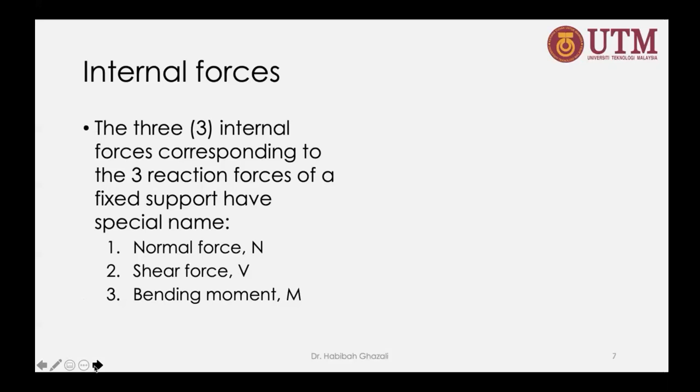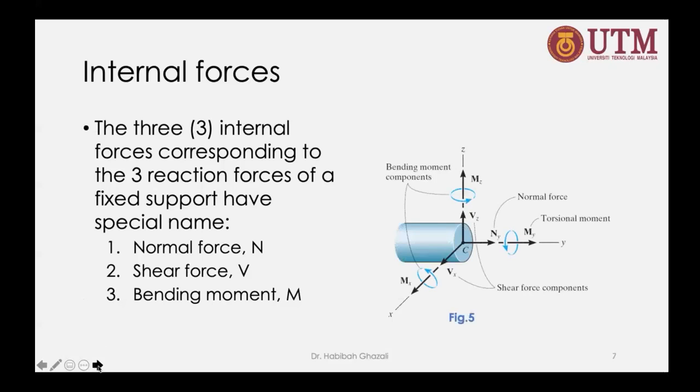So there are 3 internal forces corresponding to the 3 reactions of the fixed support. For the one acting normal to the surface where you cut, we call it normal force. And if it's parallel to that surface, we call it shear force. And bending moment is when they try to resist rotation. So that's the 3 fixed support reactions and the 3 internal forces that we're going to use here.